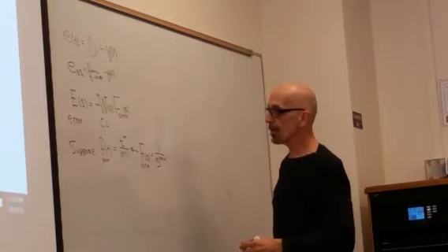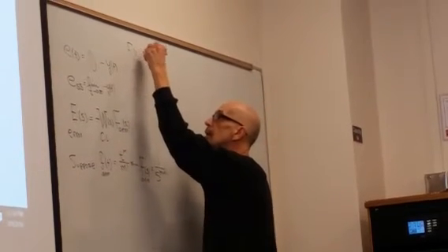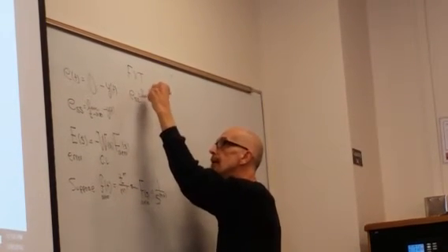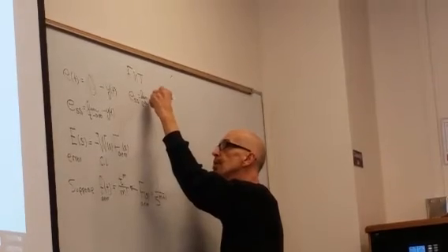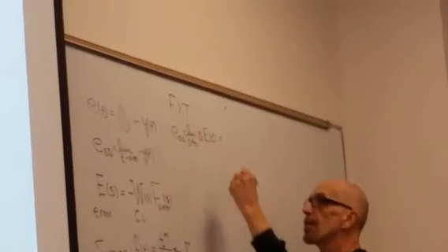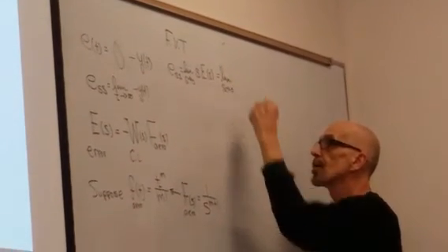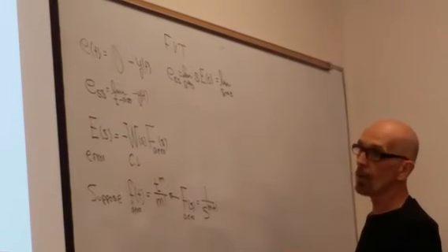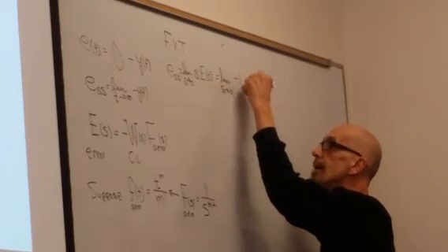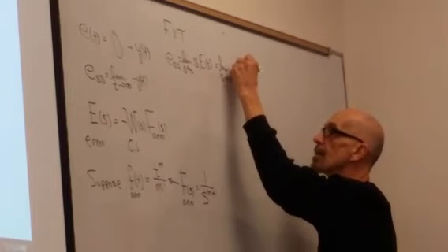Okay? And now we're going to apply the final value theorem. E steady state is the limit as s goes to 0 of s times E of s, but that's equal to the limit as s goes to 0 of what? Well, here's E of s, minus W of s. There's got to be an s here, first of all.